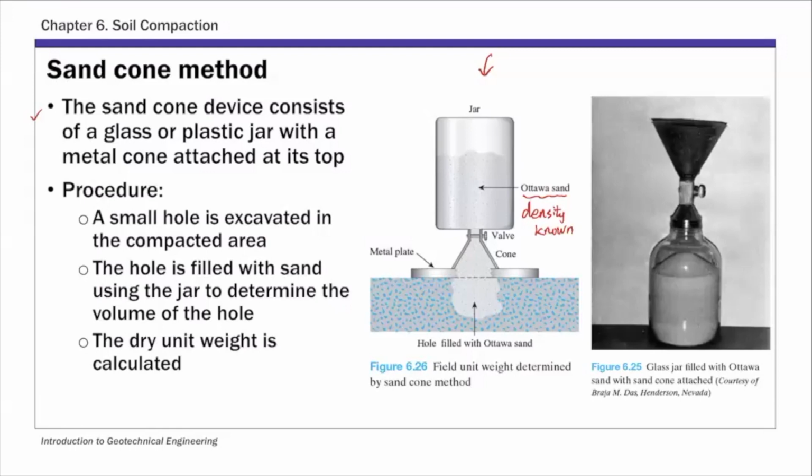And in the test, you dig a hole on the ground. You dig this small hole, and then you fill the hole with Ottawa sand using this jar here. Okay. And then you calculate the dry unit weight.